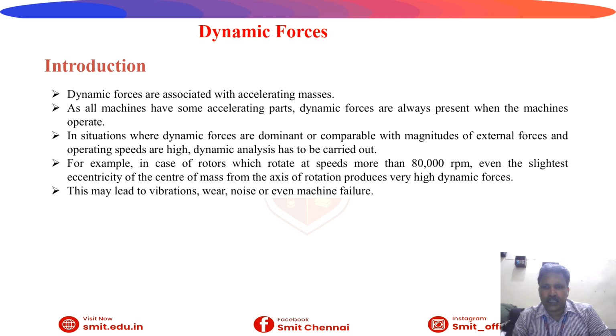When it is eccentric, it is not meeting at one particular point, it is diverted from the center point. Automatically this deviation will cause very high vibration because of the high dynamic forces arising from the eccentricity of the center of mass. So this leads to vibration, wear, and noise, or even failure of the machine.